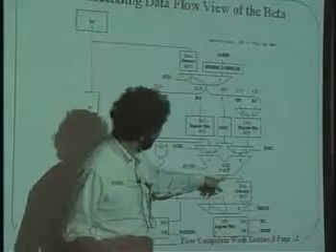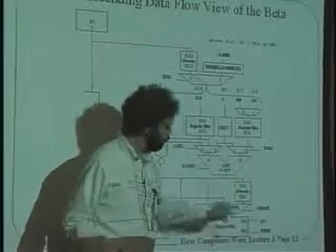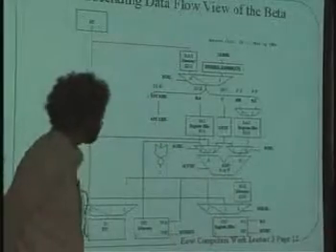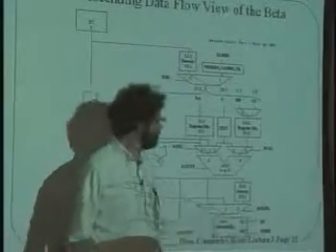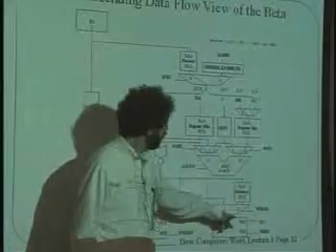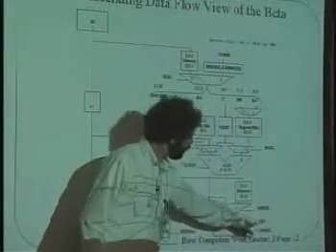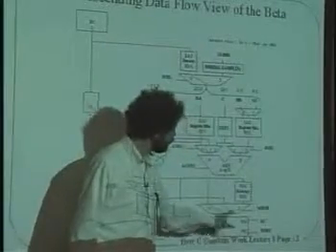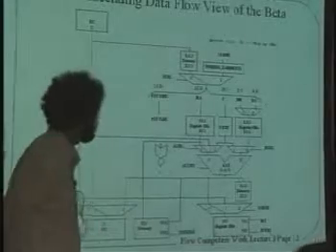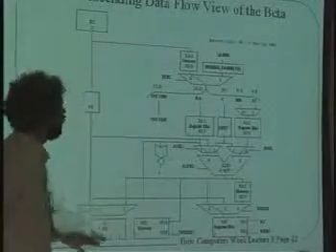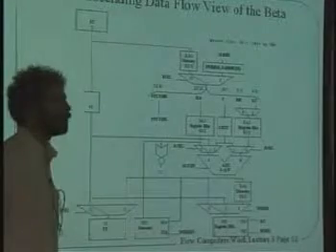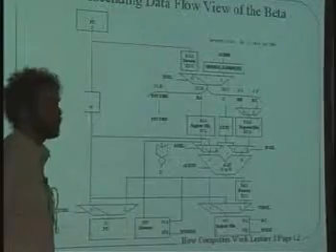And then the output of the ALU will be steered down to the right port on the register file right here. We will turn WRF on. Okay, that goes high because, in fact, when the register C code is put into here and the data that is supposed to go into register C gets put there. And finally, at the end of the cycle, when the clock goes off, click, and all three of these things take their, or try to take their picture at the same time.